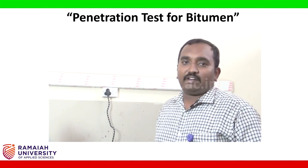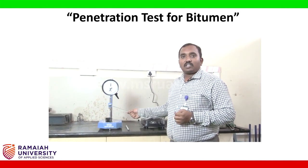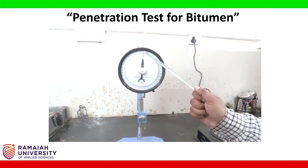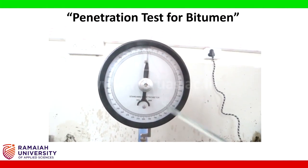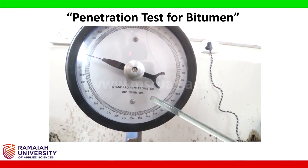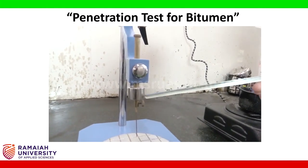The first apparatus required for conducting this experiment is the penetration test apparatus. This is a standard penetrometer having readings from 0 to 400 mm. The unit of measurement is 1/10 of a mm. There is a 100-gram surcharge weight added to the penetrometer.